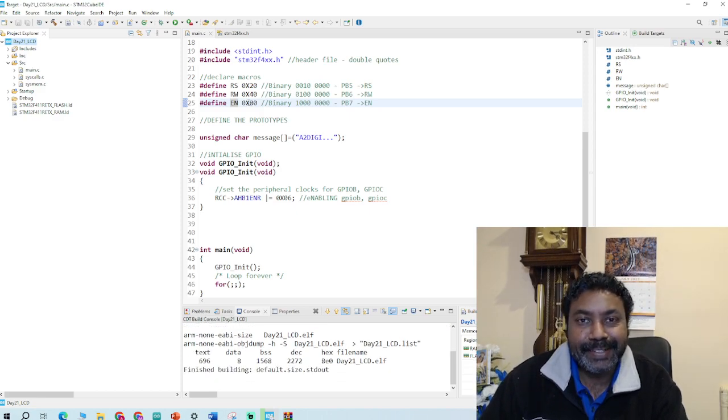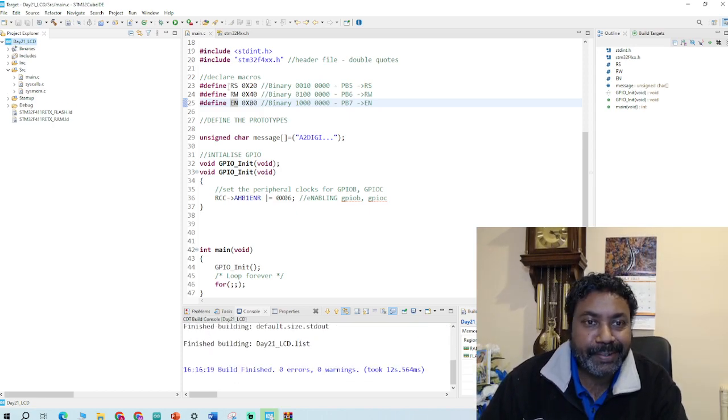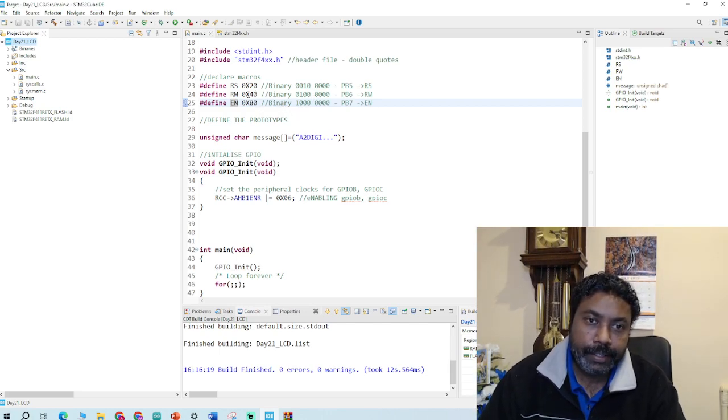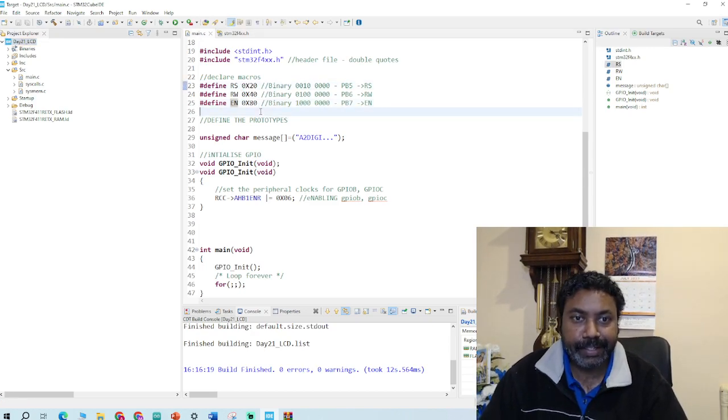So this is another example. When you copy and paste, always go back and check your register name. That's why you got the two warnings, because it said the register select was already defined and redefined again, in 3 different locations. So it didn't accept this line. It's good to check like that, otherwise after you finish about 200 lines of program, when you start to debug, it takes a long time to get that going.